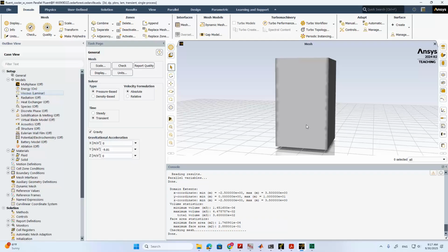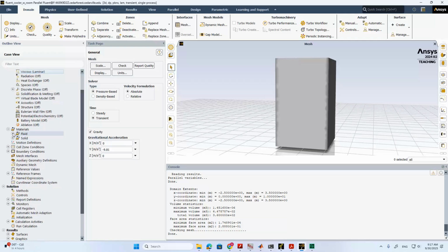We also have to solve the energy equation for not only the fluids but also the solids, like the insulation layer of the cooler, the aluminum container, those things. So here you in fact have to define many different types of materials which will be used in our simulation.